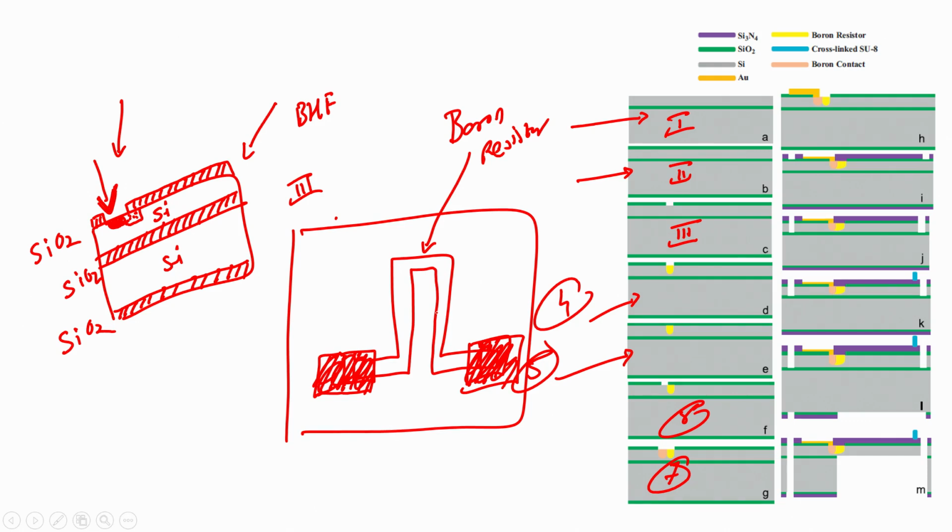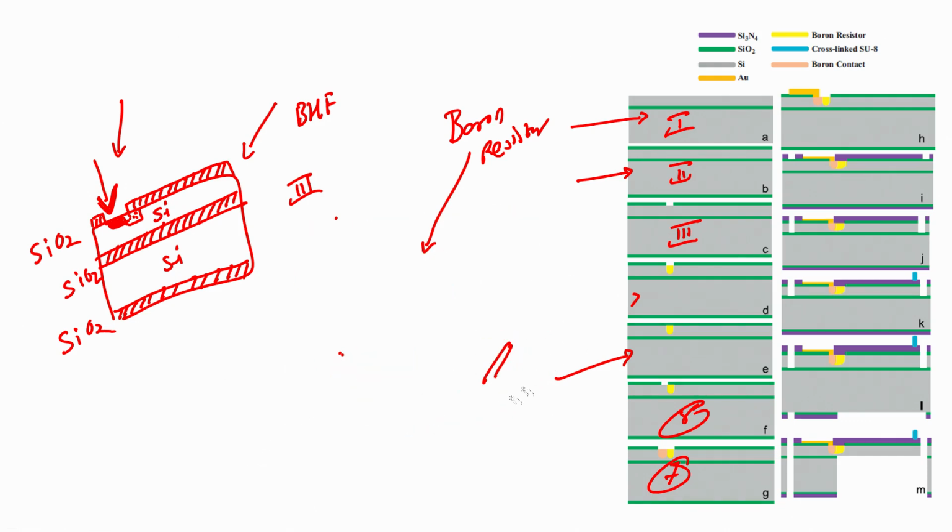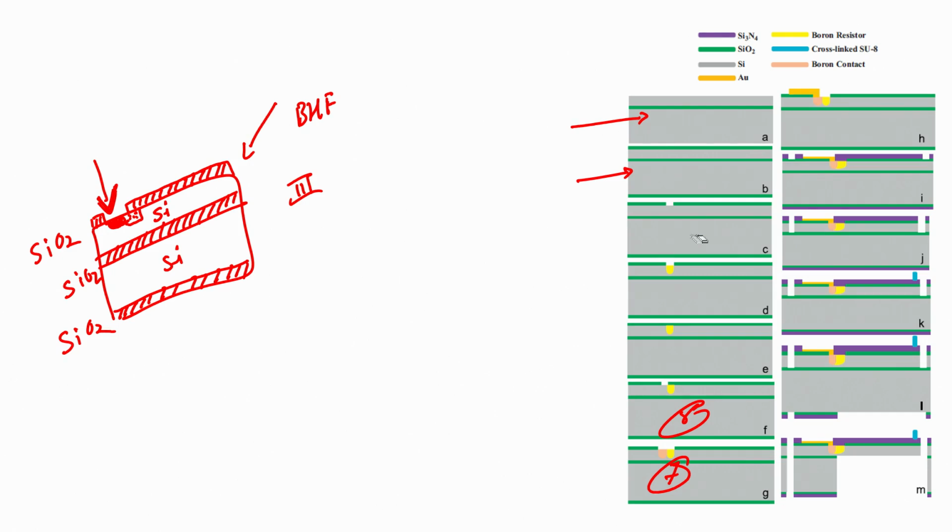Okay. So, this is the top view. You have to just keep on imagining where we are, which step, what will be the front view, what will be the side view. These are all the cross section views that you can look at when you are talking about the process flow. This is called a process flow for fabricating the piezoresistive microcantilever. So, first, second, third step is over, fourth step over, fifth step over, sixth and seventh step is also done.